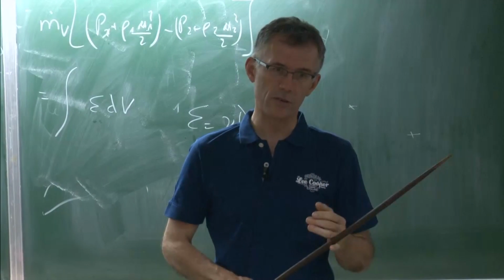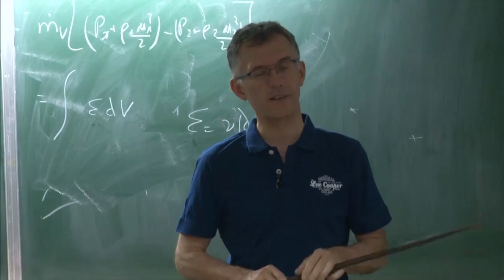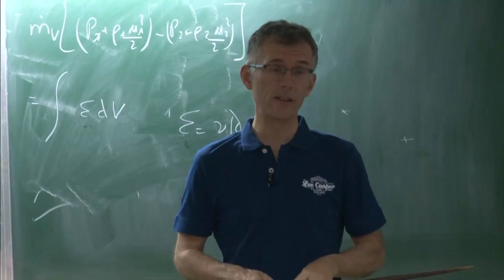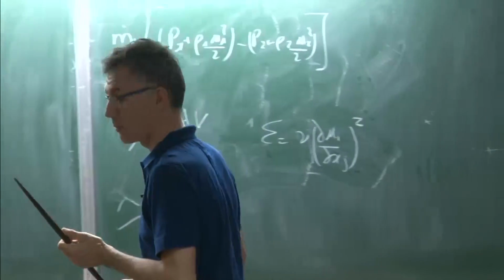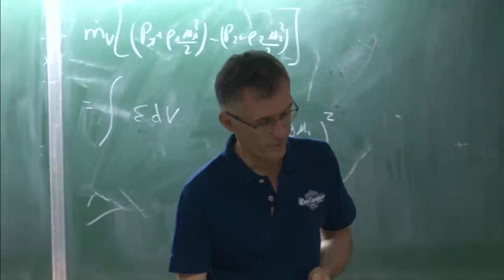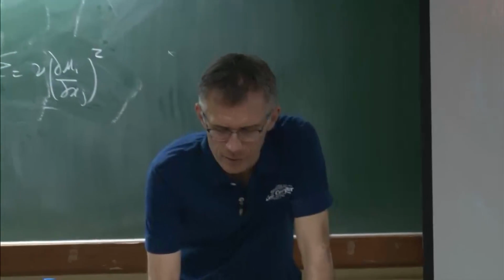I must say also that what I've shown you here is for non-reacting conditions. If you do combustion, then you're on your own again. For example, also if you do mixing, we know that it's a usual problem when we compute this. I will talk about them in a few minutes probably.